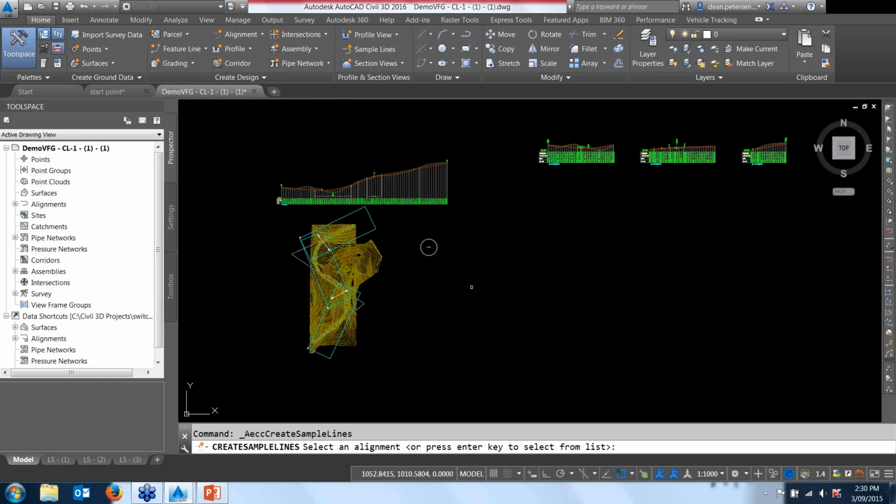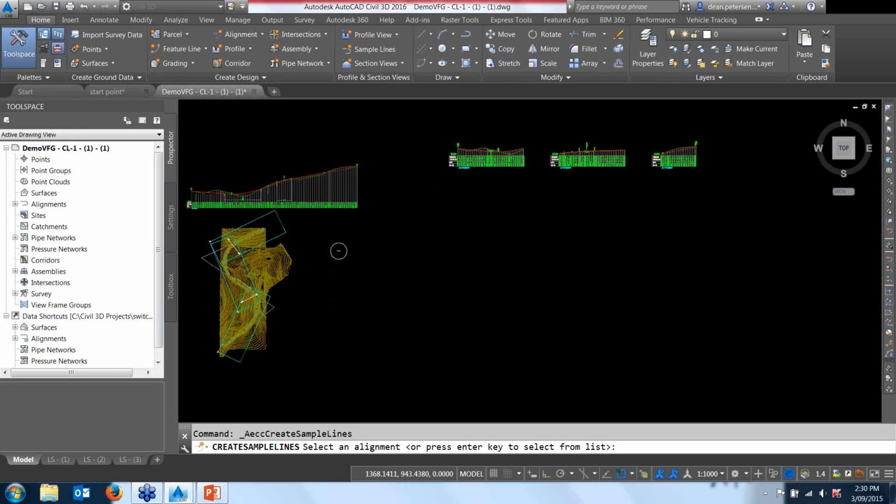Now I should say, in a section of road this long, with just 3 sheets, it may not take you much time to do that manually. And that's fine. You don't have to use the plan production tools. There's no reason why you have to. But if you've got many kilometres of road, that's actually going to save you some time. So, 3 of them, you'd probably be able to do about the same sort of speed to do them manually. But the cross sections, it's actually quite useful. So let's have a look at the cross sections.